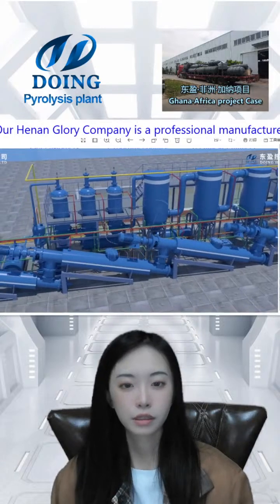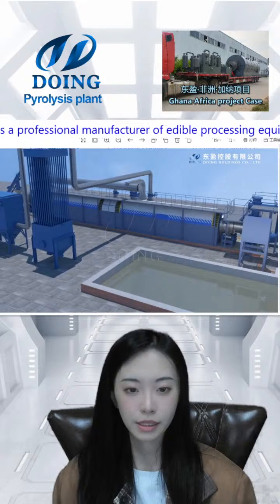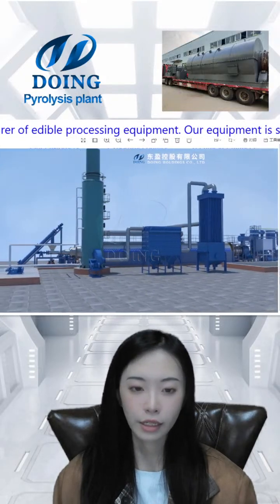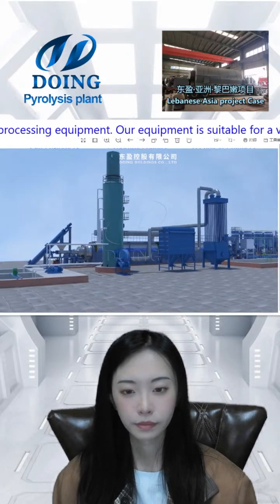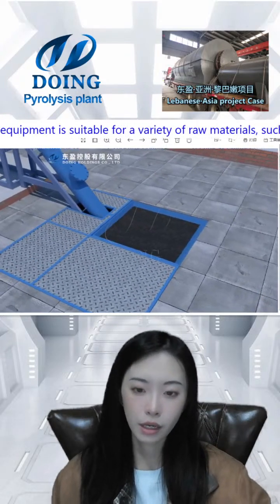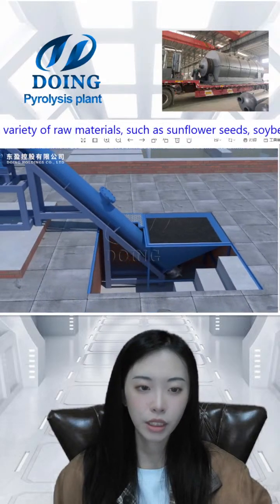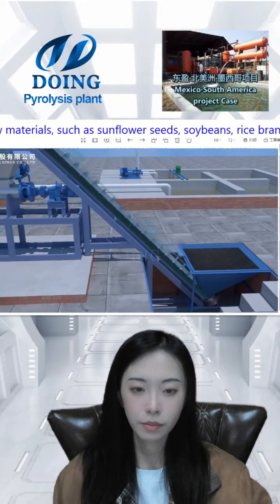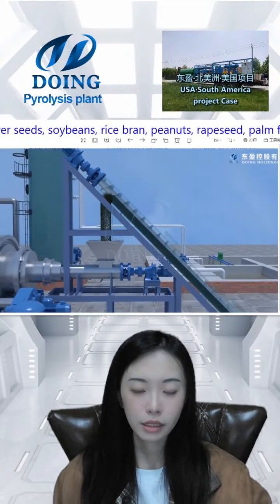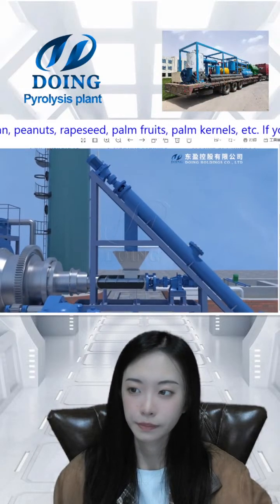We have the feeding system, condensation system, flue gas treatment system, and the slagging system. This is the purification system. Rubber powder with a diameter of less than 1 to 2 millimeters will be conveyed to the horizontal feeding angle by this rubber powder lifting screw conveyor. And then this conveyor will convey it to the reactor for heating.